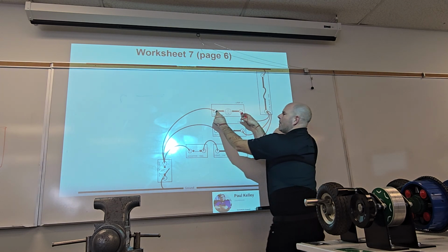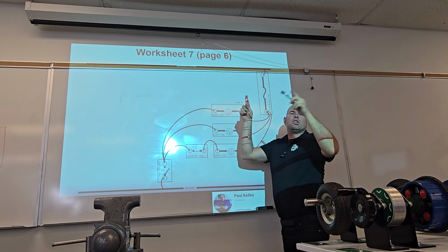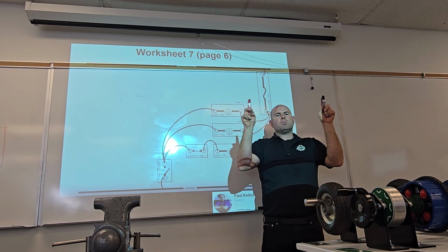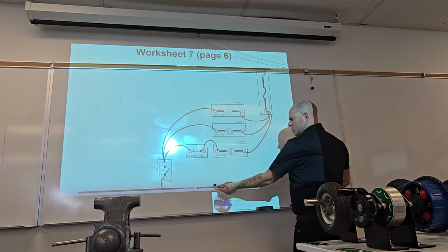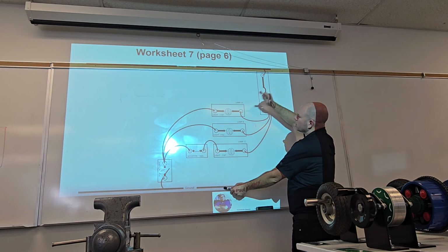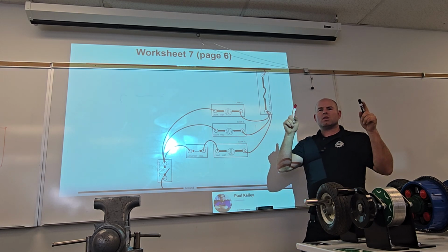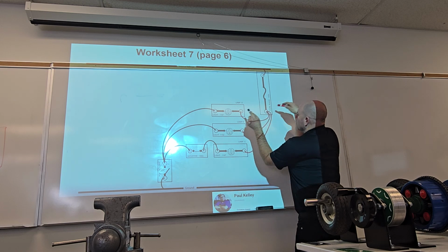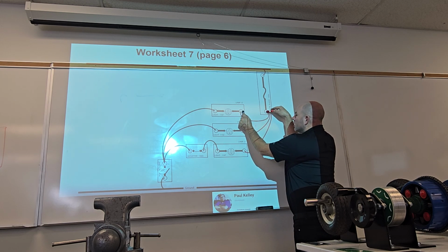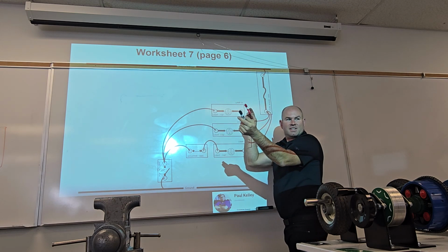Okay. How much should it drop based on the last lesson? And you're not unplugging. You don't have to. Exactly. So remember, your meter measures the difference in voltage between the 2 points. So when we're checking for available, you just hang this one on the ground and you're like 12, 12, 12, 0. Cool, that light's good. Whereas with the voltage drop, you're testing between the 2 points. You're going to be like, what should the wire drop? You tell me, what should the wire drop? Nothing. Yeah, it should drop nothing. What should the load drop? 12. Everything. Yeah, exactly. Makes sense.